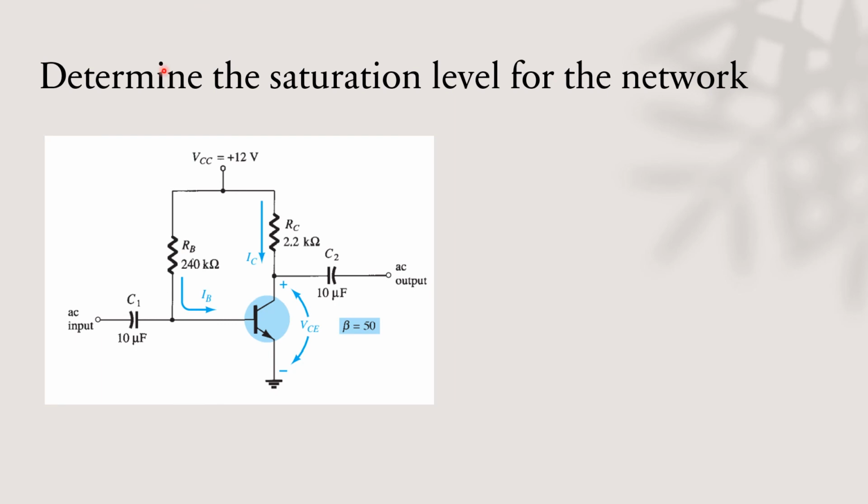Next, we need to determine the saturation level for the network. So we solve for the IC sat, the saturation point. IC sat is equal to VCC over RC.